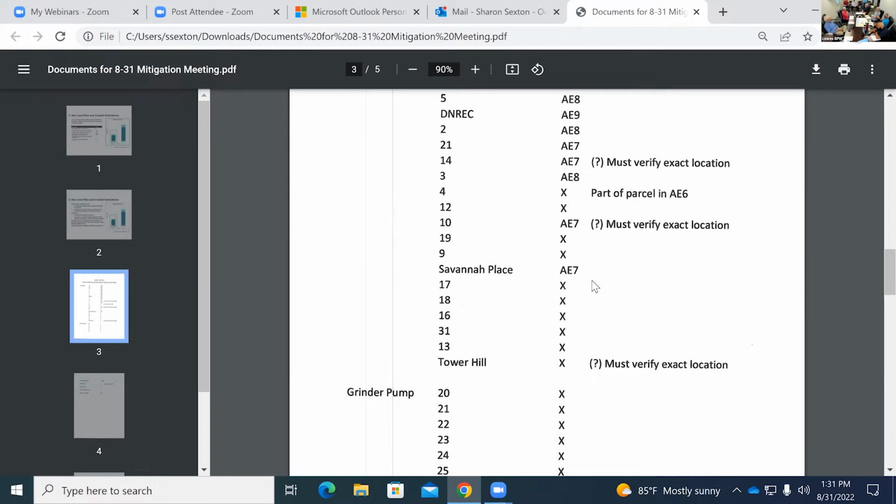Charlie, wouldn't that work? It's an approximation, and granted, it doesn't get the topography, but that's the blanket solution to it, because the elevation may already be 12, it may be 8.5. But if you build to the 11.6, in theory, knock on wood, you should be good, because if you're in the X now, the floodplain is going to creep. It may not creep that much. As I stated before, it went from 9 to 7. Who knows? The 7 may go waterward.